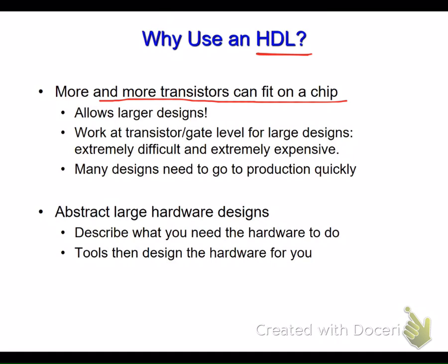In another sense, if you have a design without the language, if you are just creating the blocks in one of the tools, unfortunately, the migration to another tool will be so difficult because they might not have exactly the same library. What does it mean, the same library? To give you an example, you have in your design an AND that has 3 inputs, but maybe the other library only has ANDs that have 2 inputs. Then when your design needs to be transferred there, you need to use 2 ANDs instead of just 1 AND with 3 inputs, or 1 AND with 4 inputs, and so on.